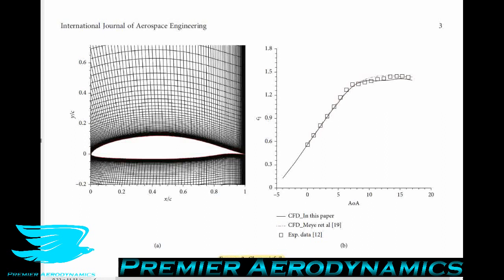Also, it has a maximum camber of 4.5% occurring at 42% of the chord again. So where we have the maximum thickness, we also get the maximum camber. So that's quite interesting. Now, looking up the performance of this airfoil, I looked it up in some books and found that the maximum lift coefficient is usually around 1.3. In this research, they found a very similar result, which we'll cover in a second. The minimum drag coefficient is 0.01 often.